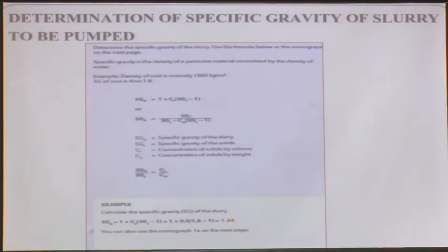Now, this is important. This is the linkage between specific gravity, density, the percent solids by volume and percent solids weight by weight. So that we have also seen, we have seen the linkages when I discussed the mill. So this is another way of doing it, it also can be used. So if one figure is known, the other can be known, provided the density of the solid is given, right.